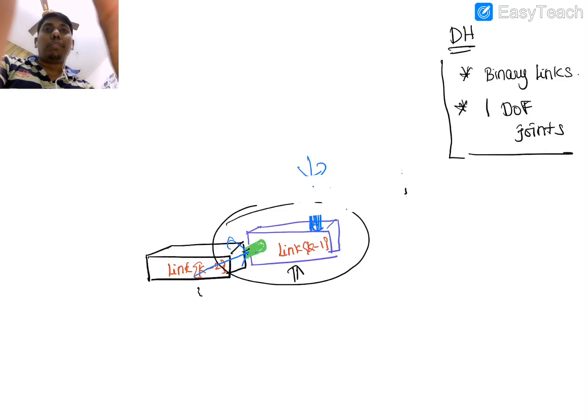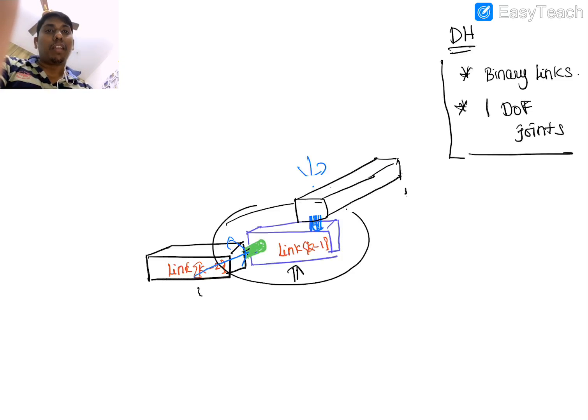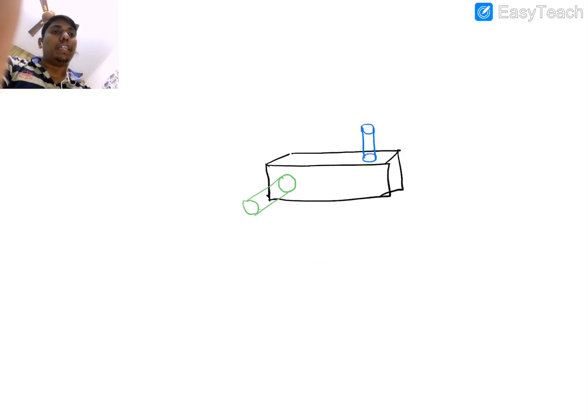So I am taking the black color as a block, and you can see that this is the position after rotation. So this is the third body. Okay, the third body is oriented like this. The first body is oriented like this. The second body is oriented like this. In the sense, when I draw the frame diagram, you can see the third frame, we call ith axis. Okay, so the ith axis where the xi is going like this.